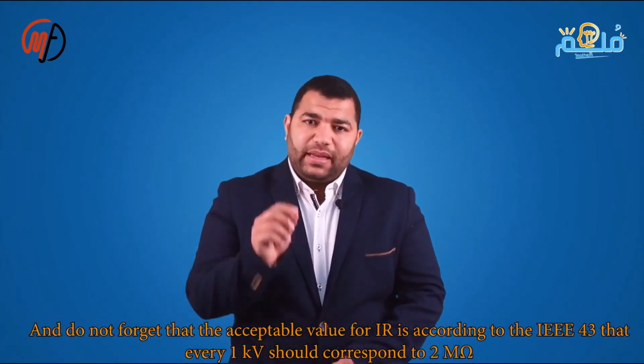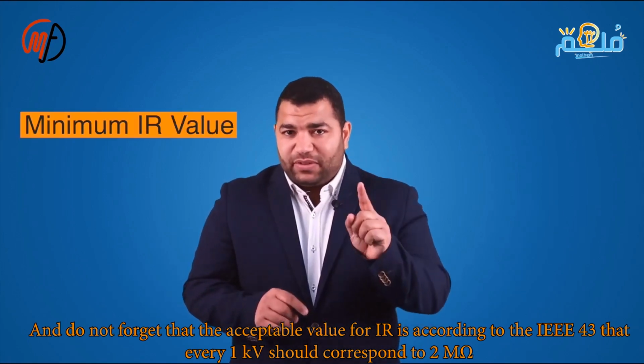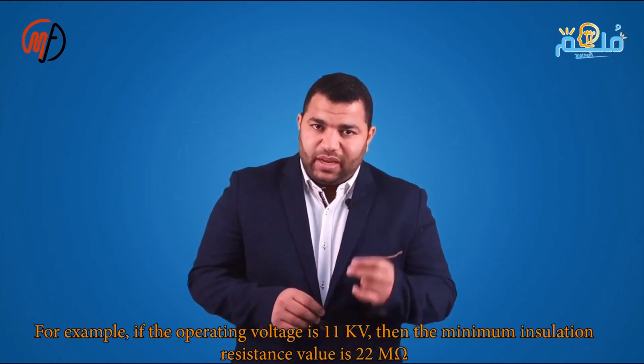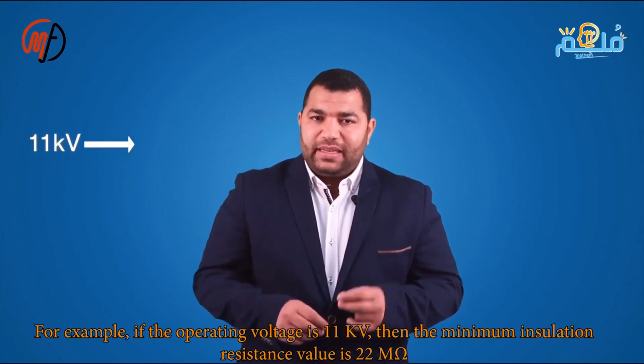We must remember that insulation values should match the rule: every kilovolt equals 2 megaohms. For instance, at 11 kilovolts, the minimum insulation resistance is 22 megaohms. Tested for 1 minute, faults decrease, with resistance changing over time affecting insulation quality.